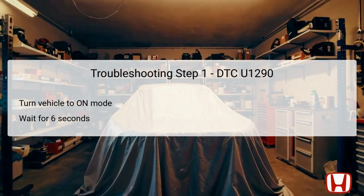The first step in troubleshooting DTC U1290 is to ensure the vehicle is properly powered. Begin by turning the vehicle ignition to the on mode, which activates the electrical systems without starting the engine. This allows the vehicle's control units to initiate their processes, including the climate control and front seat heater control units.